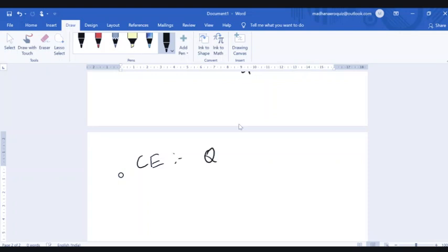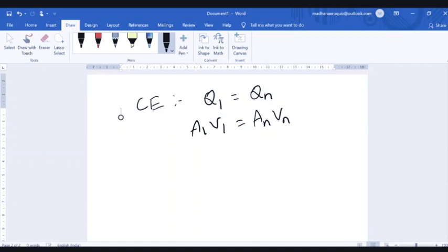So the discharge at section 1 is equal to the discharge at n sections, because we are considering n number of sections. As of now, you know what is meant by discharge. Discharge is nothing but area into velocity, and at every section it is the varying area multiplied by the varying velocity. This area is nothing but the cross-sectional area, so again we are simplifying it as pi by 4 d1 square v1. Here it is also pi by 4 dn square vn, and again these two get cancelled.